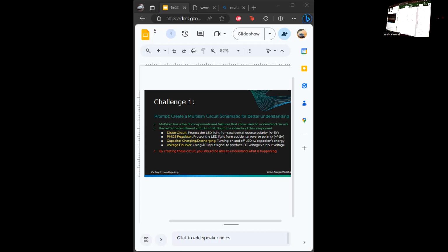You kind of think of this C, there's polarities on capacitors, right? If you use one in the lab, there's a plus and a minus. In this case, it's not really accurate. The reason this works in Multisim is because Multisim needs a ground in order to calculate where all the other voltages are. This ground is a reference ground. That means from this point on, this is 0 volts and everything else is going to be higher than 0 volts, which technically means you don't need one here. So this is not 0 volts, but this is always going to be 0. Multisim does a lot of calculations to compare everything to 0 volts.